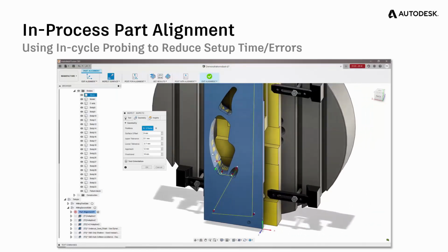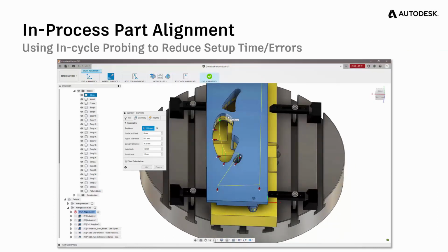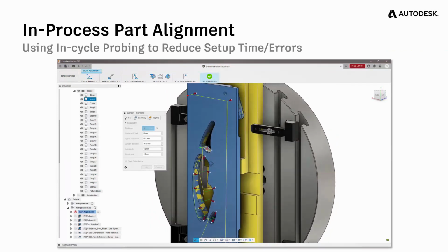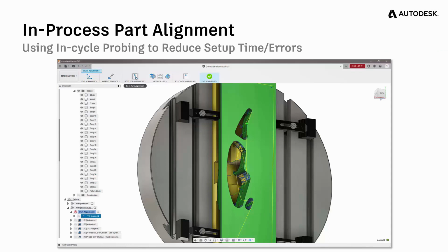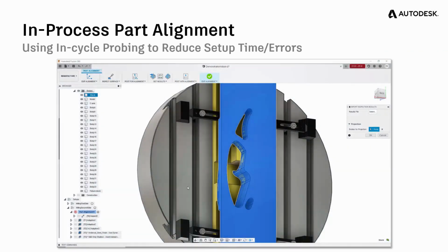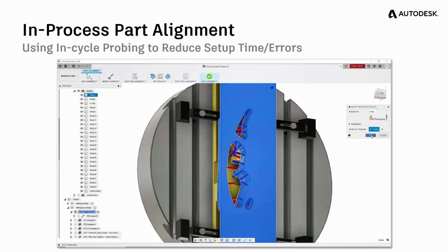Now, once those probe paths have been defined and the NC program has been output to the machine, it can be run. The machine then generates a series of measurement points as a text file, and that text file can then be re-imported back into the Fusion 360 program. Now, crucially, Fusion 360 will then display the measurements as a series of color-coded markers. So you'll be able to identify errors, and you'll see those appear in a moment. So here you can see we're selecting the measurement file, and then after a brief delay, you can see them